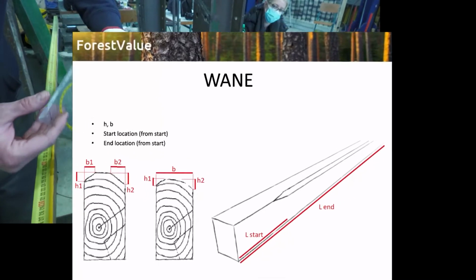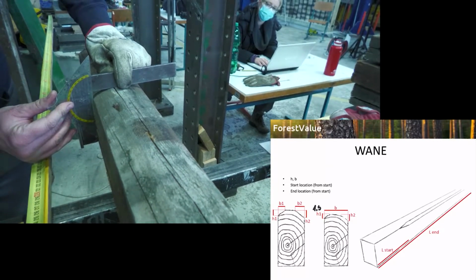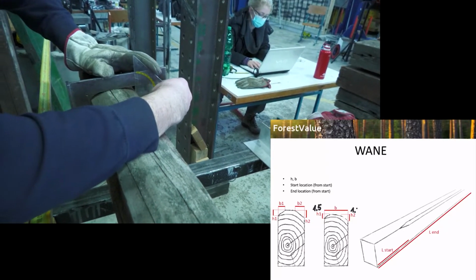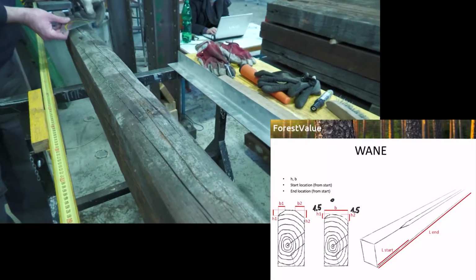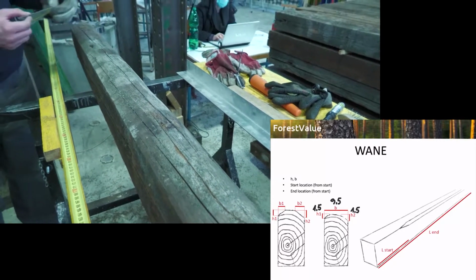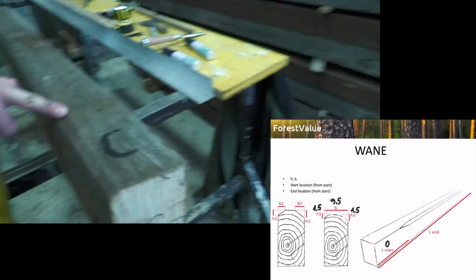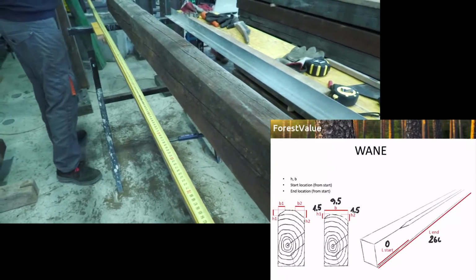We measured the missing cross-section due to wane. This was done by adding all the missing widths and thicknesses of a cross-section where this effect was at a maximum. The entire length of wane was measured by recording the beginning and the end location of the wane from the start of the specimen.